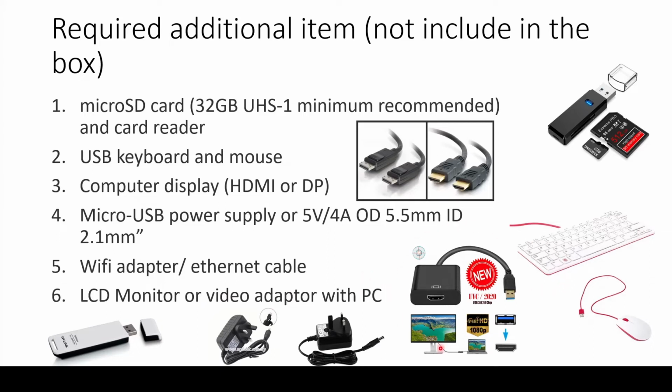This is an example of a video adapter. It's connected to your PC USB and the output HDMI from the Jetson Nano, or digital port. If you are using a digital port, you need to have a video adapter that supports digital port.